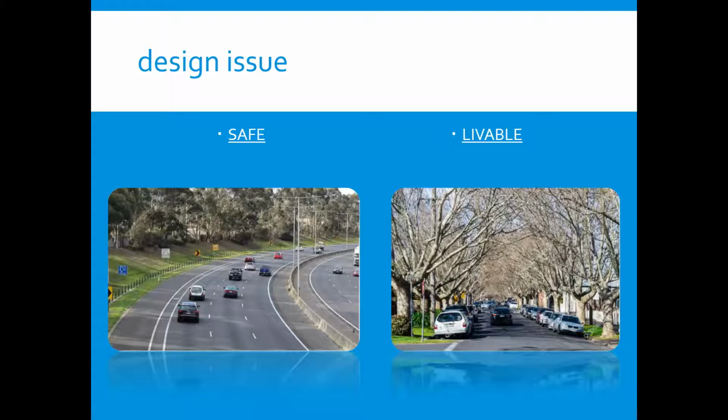Ensure that all roadways are forgiving, so that such errors, when they occur, are survivable. After I declared those fundamental principles of passive safety, the logical conclusion would be to enhance safety by widening lanes, shoulders when they're provided, and providing a clear zone. The clear zone concept will be discussed during my lecture.